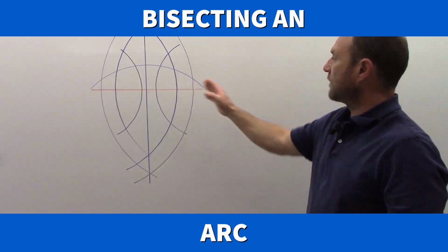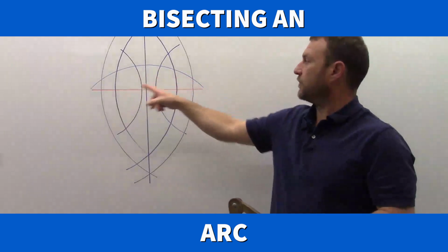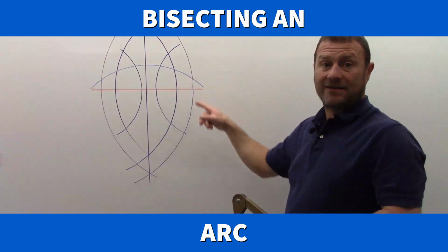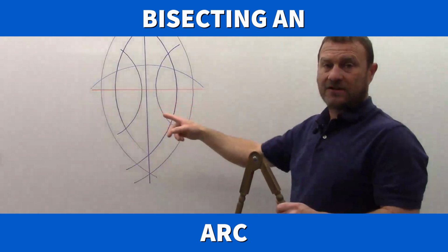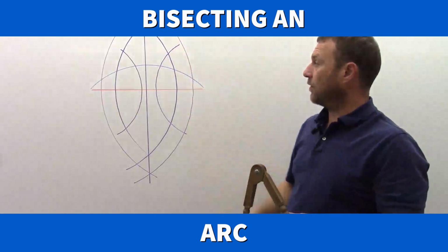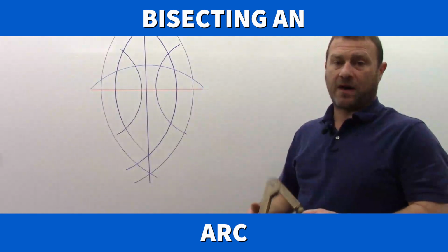So anywhere I swing those, as long as I swing from the two outside points of the arc or line, and I keep that distance consistent from side to side, I'll end up with a cross point above and below. And if I join that, that's my bisection.